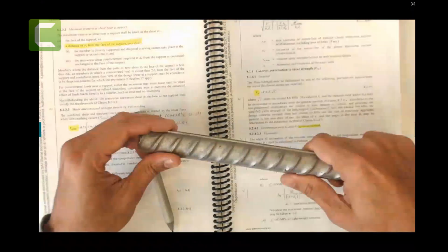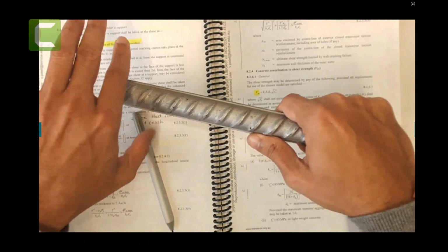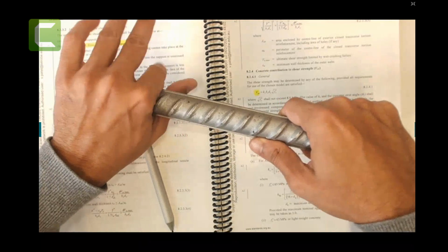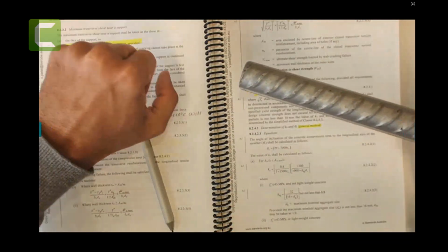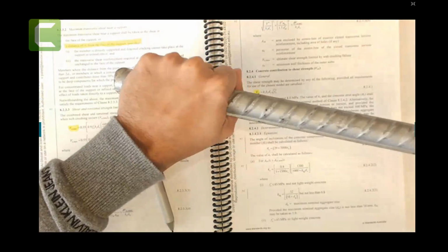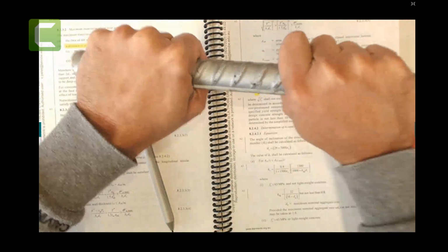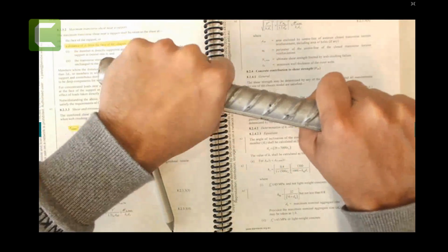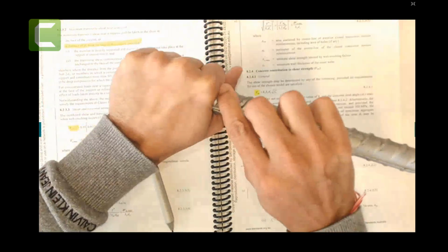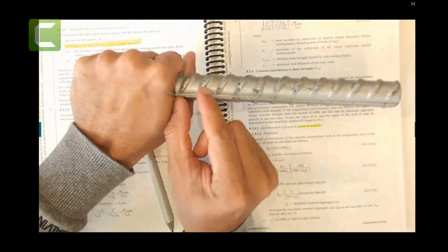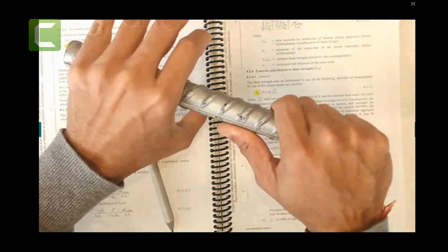So for example, let me put this one here. Let's say this is my rebar, and someone says okay, I will not provide enough development length. Then I have only that much grip, and I can easily pull it out. Look at that. It's very simple to pull out. But if someone provides adequate length, the concrete is holding tight. It's very hard to pull out, because you have enough grip, enough development length to hold your steel bar. So at this point, when I pull it, it is going to yield. That's what we wanted. We want to yield that bar, right? I hope you understand that.